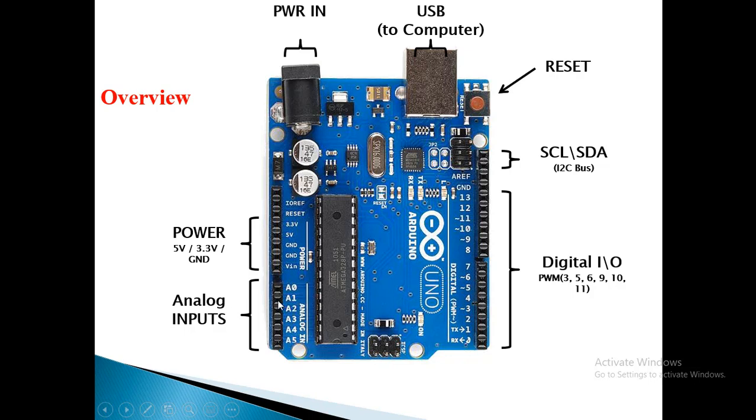And here in the lower left corner, you will find some analog input pins like A0 to A5. You connect sensors to read data from the physical world. And you will find the power supply pins: 3.3 volt, 5 volt, and ground. So there are lots of options to supply power to the Arduino: 3.3 volt or 5 volt to the ground, a 5-volt DC adapter with this pin, or power from your computer through the USB port. So that is the basic overview of the Arduino.